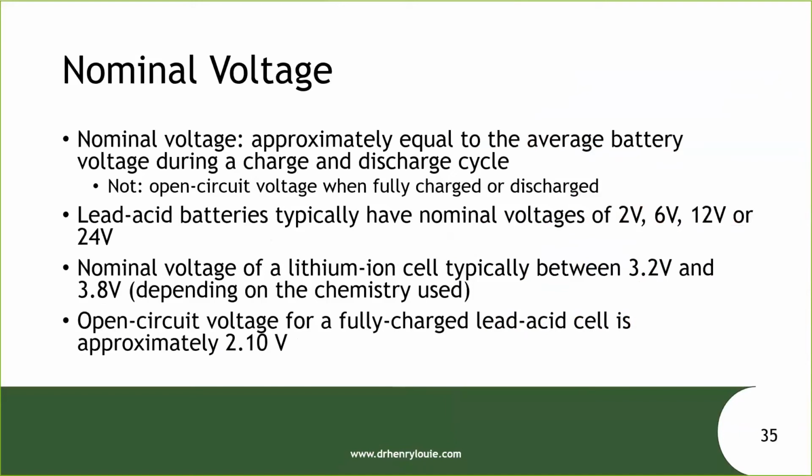it's approximately equal to the average voltage of that battery when you do a charge and discharge cycle. So we shouldn't interpret the nominal voltage of a battery as the open circuit voltage. That's not the case at all.